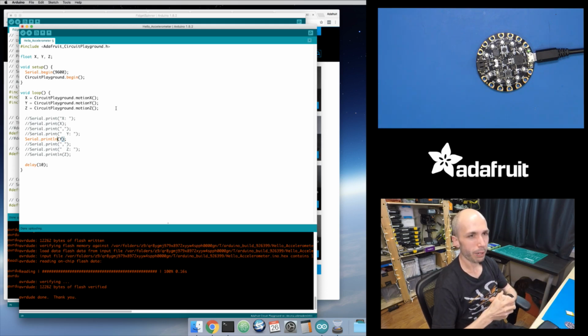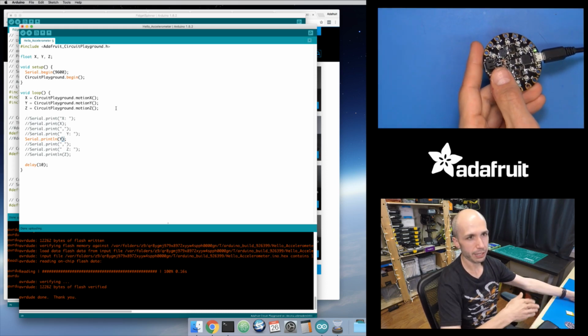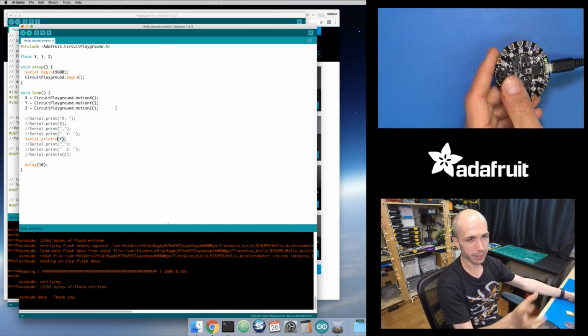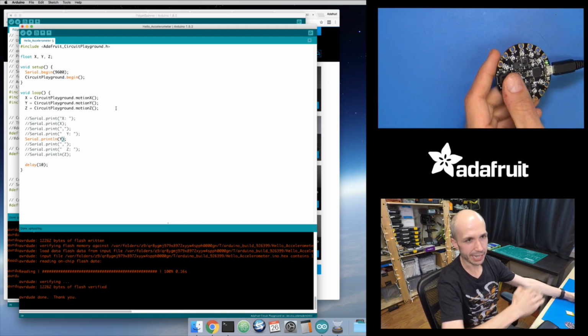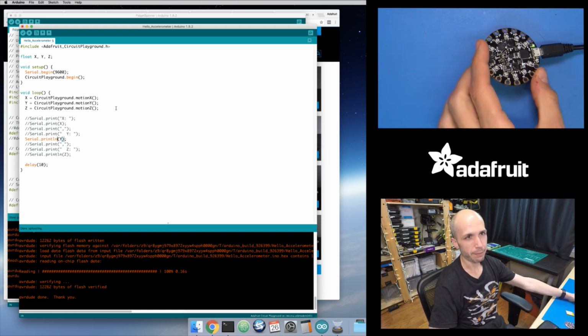And so I was just thinking, well, what if I filtered the values? I just took the average of the last, let's say, 10 accelerometer readings. So I average all those out. That's going to give me a less quickly changing value. It's going to give me the average, so that if I have some random noise of just moving the board around, it's going to smooth that out so that I don't see all these jaggy spikes. It's going to look at all 10 of the last readings, and if all 10 of those are really jaggy and high, then okay, it's naturally going to push that average value up. But if only one of them was a small spike, that's going to get filtered out, and it's not going to impact that value as much.